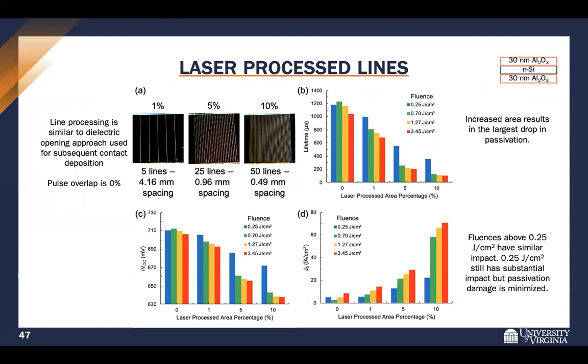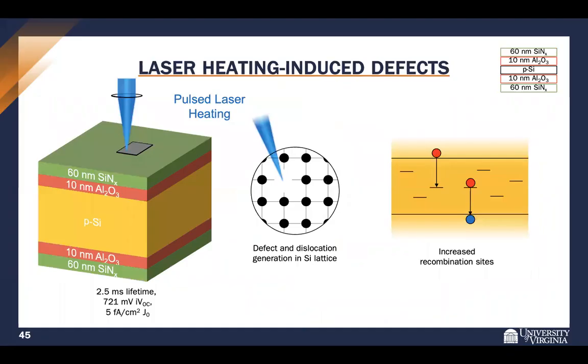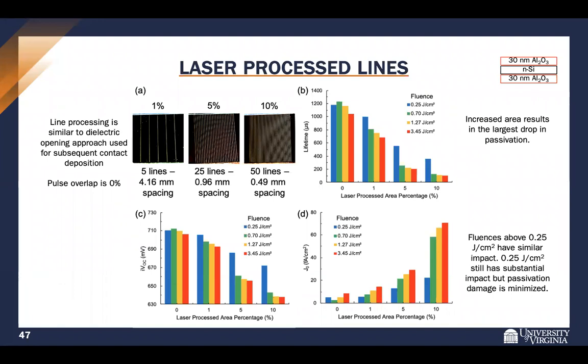What do you think the cause of that is? Because it could be a lot more economical with the less heat load, and I don't know how the throughput or reliability issues might be. What do you think is the key to getting this laser processing into the production line for solar cells? Well, one issue is the thermal process is down to a science now. I believe it's something like 1 to 2 seconds per process for a wafer. So you need to make sure whatever laser process you incorporate is as fast or faster than that. Also, a lot of these furnaces can process multiple wafers at a time, whereas one laser can really only address one sample at a time. It can do it quickly, but if you have hundreds of wafers going through, there are issues with that. You can always get more lasers, but that becomes expensive.